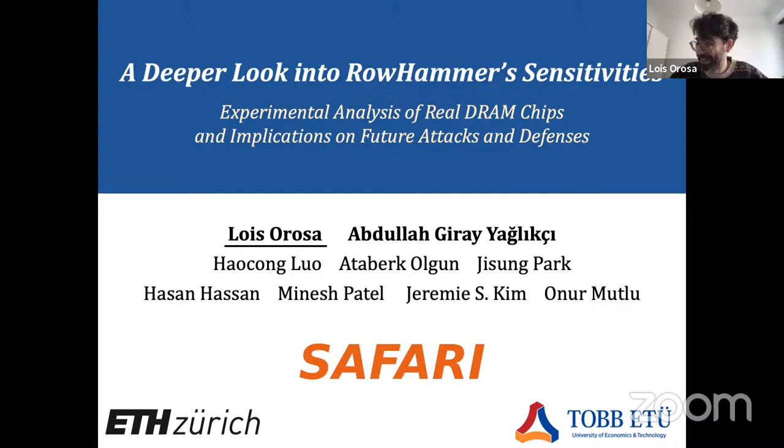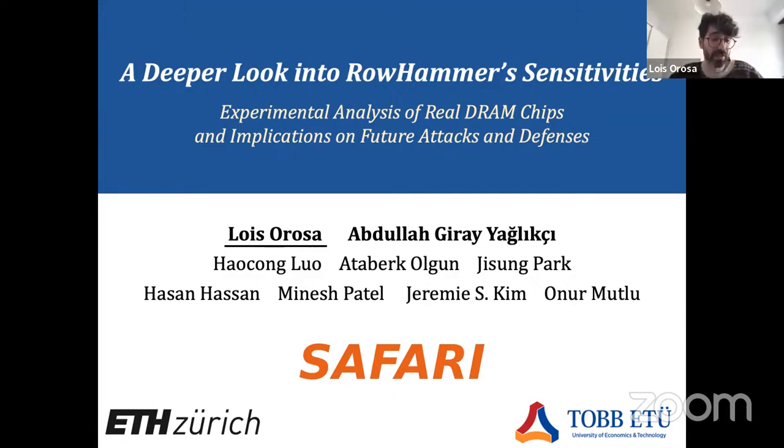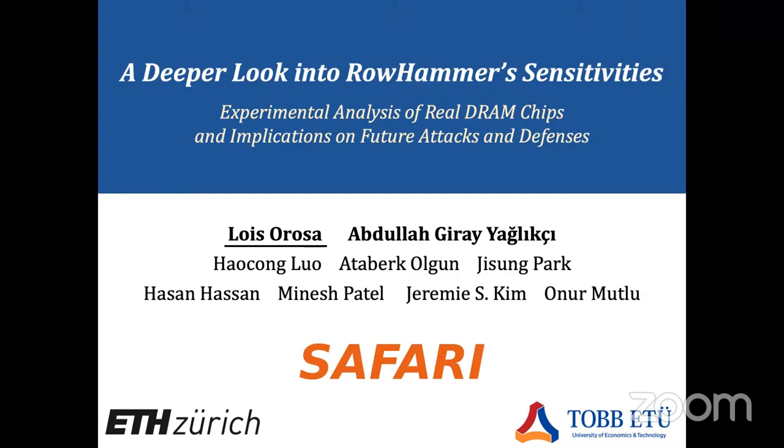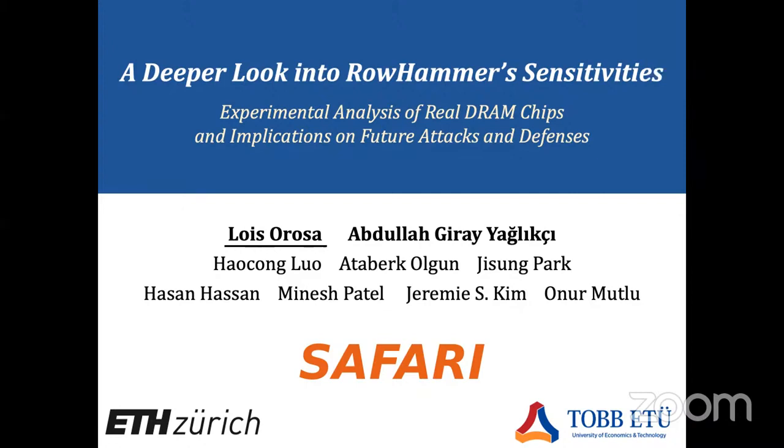Yeah, sure. But I just wanted to also understand if these RowHammer vulnerabilities are also relevant to something like a supercomputing center. Yeah, sure. This is relevant to all DRAM modules in the world as far as we know, and the RowHammer vulnerability worsens when the technology node scales, right? Because everything is closer together, and this is a bigger issue. Although manufacturers are trying to mitigate this issue, there are many papers like this one and other ones that demonstrate that the problem is still there. So still there, yeah. Okay, yeah.